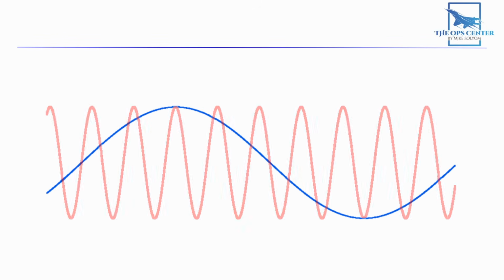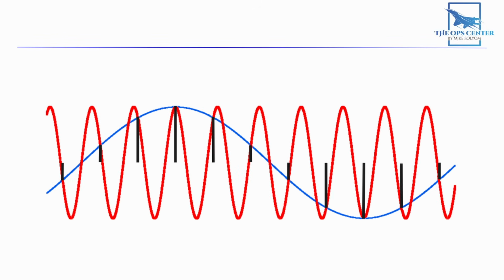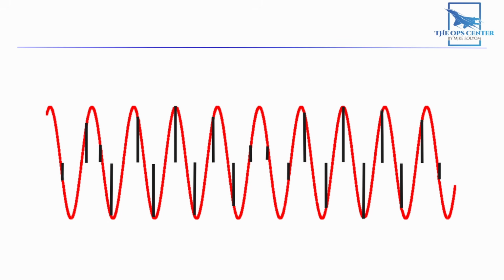There is a solution to these ambiguity challenges. When you increase the pulse repetition frequency, then you take more samples, and then these blind speeds move farther apart. This gives you a broader range to work with. Increasing PRF can help if you have a target with a high radial velocity. But it has a big downside too.